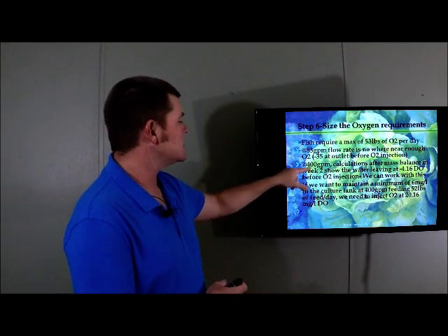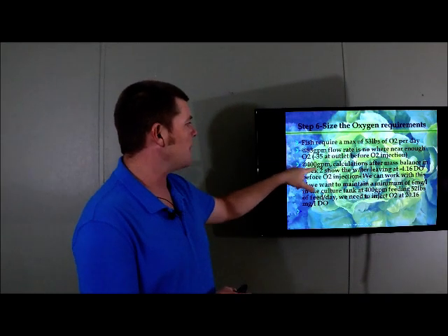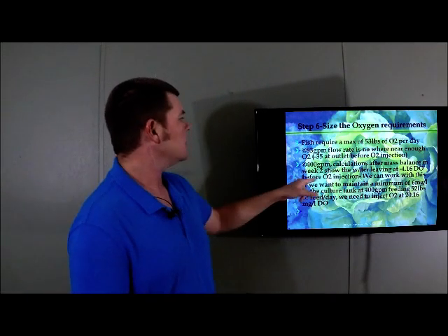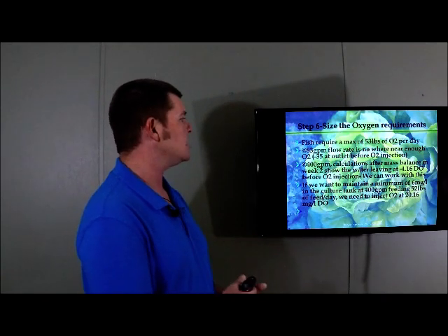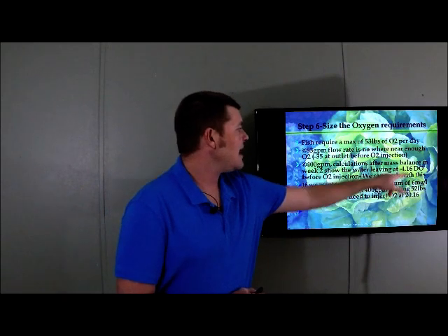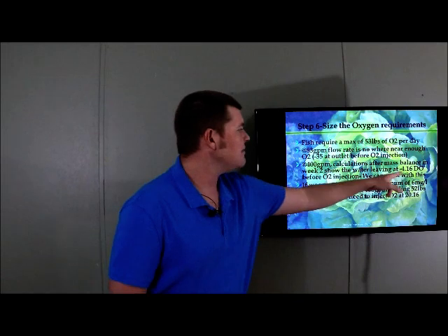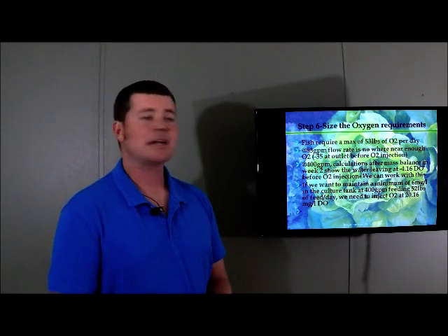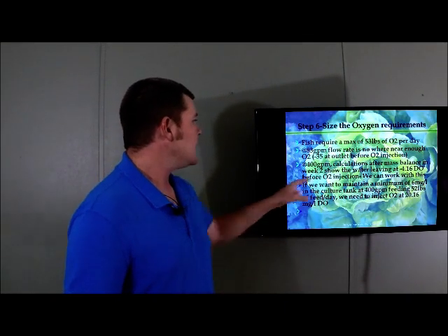So if we increase this to 400 gallons per minute, okay, and this might take you doing a couple calculations, slowly increasing it to see where the numbers fit. At 400 gallons per minute, the calculations after the mass balance that we did in week 2 show that if the water is coming in at 10 milligrams per liter, it's going to leave the culture tank at negative 4.16 milligrams per liter before we inject oxygen. But that is actually something we can work with, okay? We can work with this.